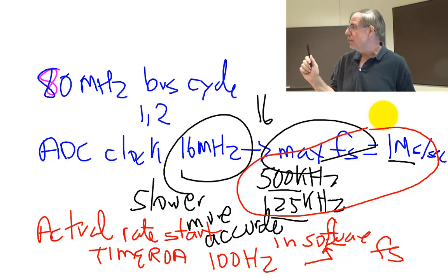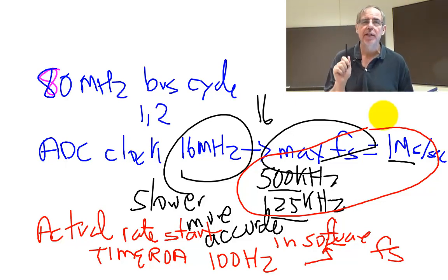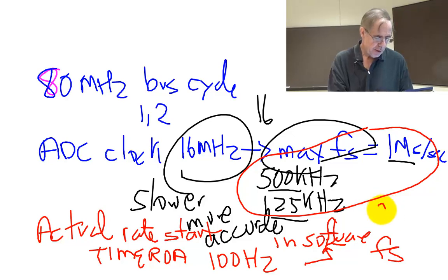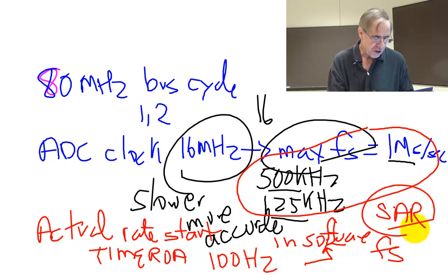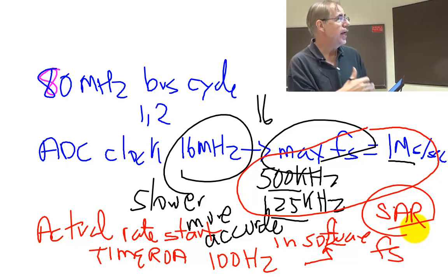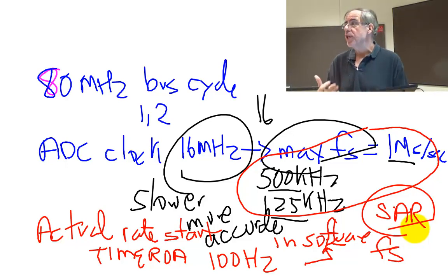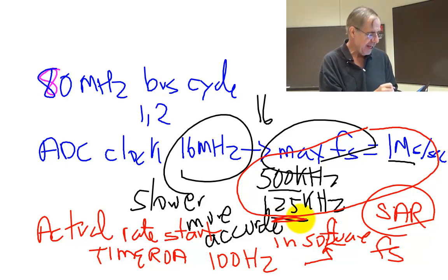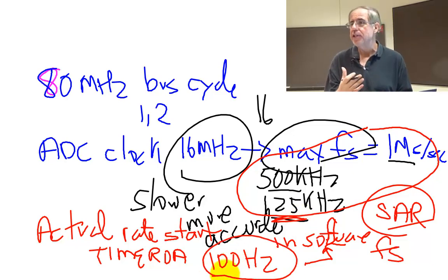But one more thing before I get back to teaching, and that is, how else can I improve signal to noise? The hardware averaging. The hardware averaging register, which can average up to 64 samples, is a wonderful thing to do in this lab because it can sample at 125,000 samples per second, and you only need 100 samples per second.